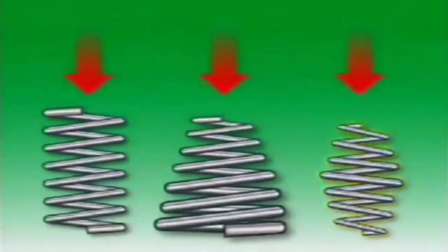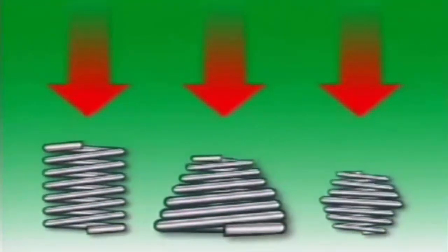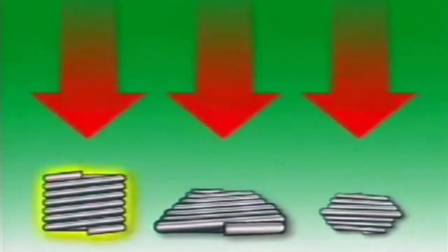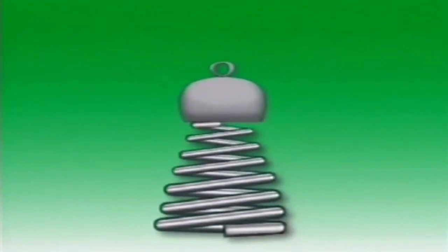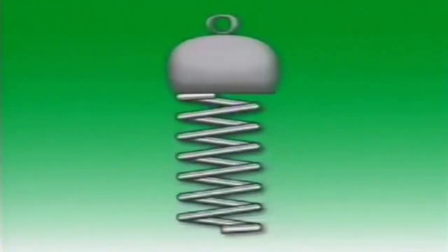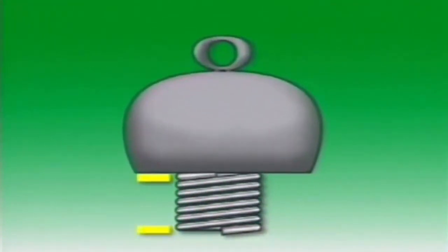As conical and barrel-shaped springs compress, they collapse into themselves. This gives a longer suspension travel for the length of the spring than for a cylindrical spring, which gives a softer ride for light load situations and a harder ride for heavy load situations. As a cylindrical coil compresses, it can become coil-bound, which limits its travel.